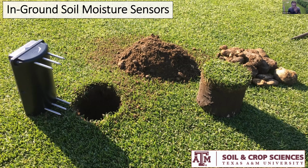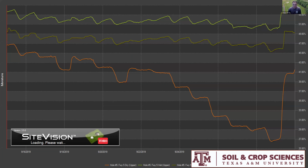This is just an example of the in-ground soil moisture sensor that we're using in a study that we're conducting up there. We placed each one of these sensors within a soil moisture class that we created on one golf course. We're currently doing it on one golf course. This is just an example of one fairway where we have 3 sensors. We created 3 soil moisture classes: a wet class, a moderately wet class, and a dry class. The wet one's this top one, the moderate's the middle one here, and then the orange one is the dry class.